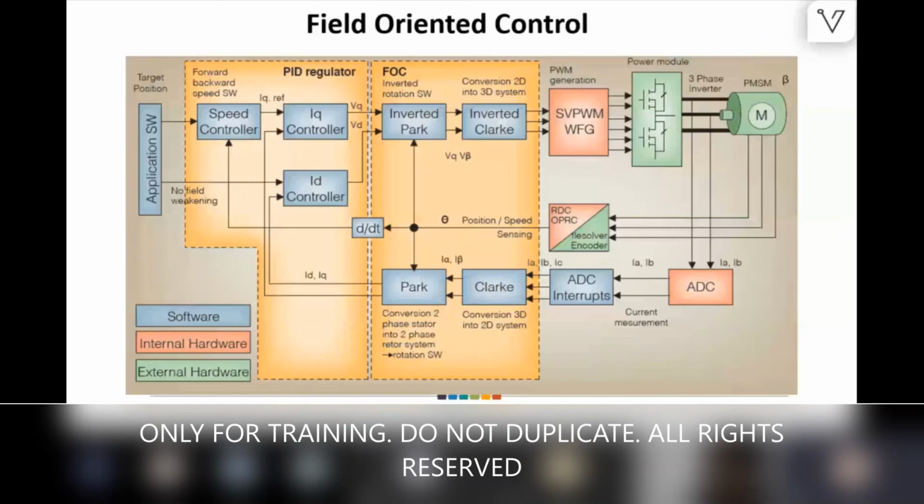At the inverter level, the software and everything will be implemented. The resolvers and ADCs will all be implemented. The resolver takes the theta angle, then two phases will be sensed. Those will be converted through Clarke and Park, inverted, and we have PID controls here. If you want to understand all these control strategies in detail, we'll have a deep session sometime, or if you want to implement this somewhere, we can have these sessions.